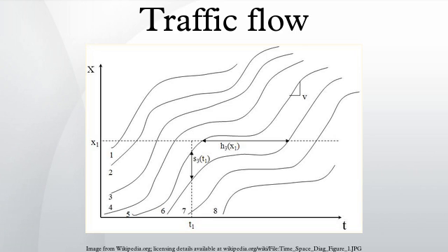Riemann's problem. Imagine a scenario in which a two-lane road is reduced to one lane at point X. So from here on the road's capacity is reduced to half its original. Case 1: later along the road at point X1, the second lane is opened and the capacity is restored to its original. Case 2: in case 1, there is a bottleneck limiting the flow of traffic, which causes an increase in the density of cars at the location. This causes a deceleration for all oncoming cars traveling at speed Vf to slow to speed Vd. This shock wave will travel at the speed of the slope of line UD on the fundamental diagram.